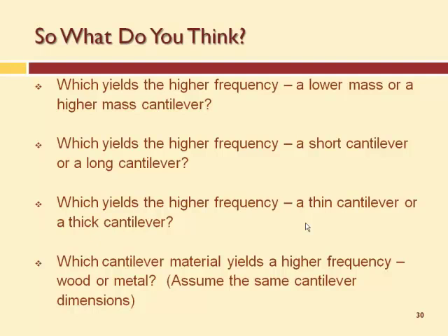If the width goes up, it does get stiffer, but then it also adds mass. They compete. Which one wins the race? You're going to do that in class, okay? Okay, which cantilever material yields a higher frequency, wood or metal? Assume everything else is the same. Metal. Good.